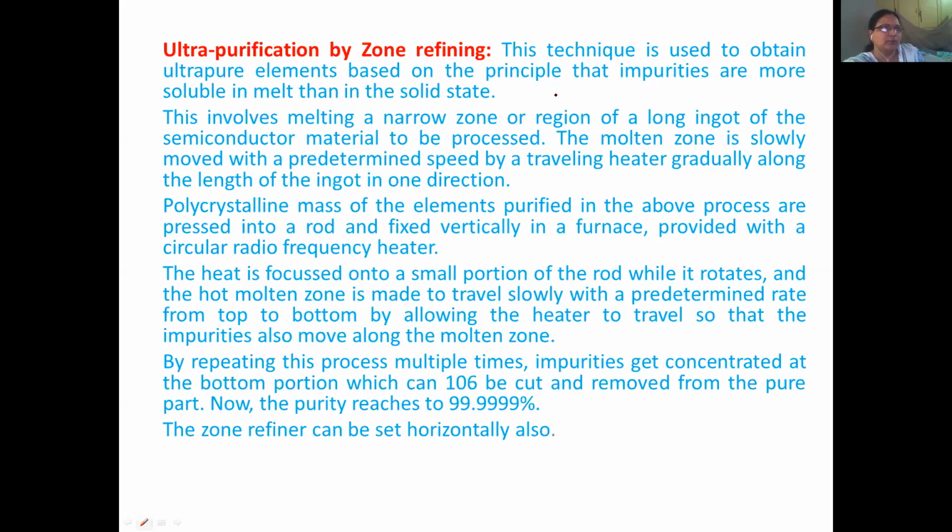So this is the main principle of zone refining technique, that impurities are more soluble in the melt than in the solid state. That means when it is in solid state, there are no impurities, whereas if you just melt it, that melt has impurities present in it. So this is the main principle of zone refining technique, that impurities are more soluble in the melt than in the solid state.